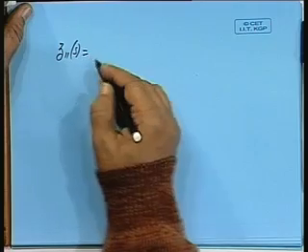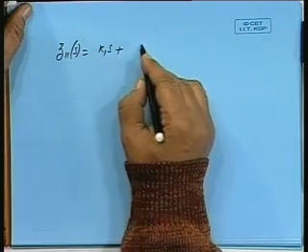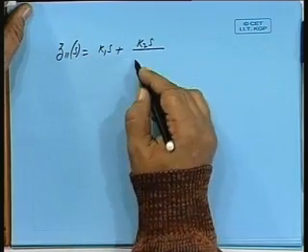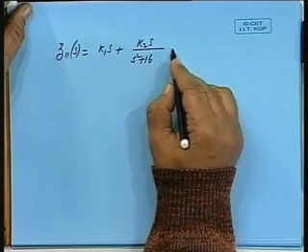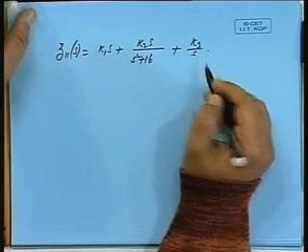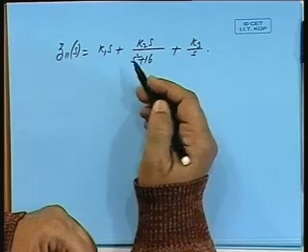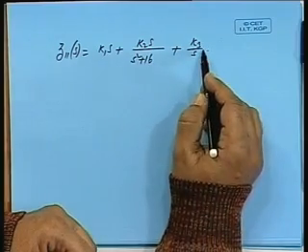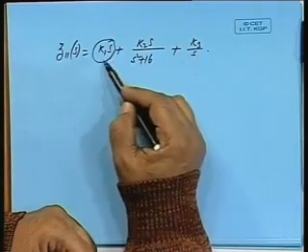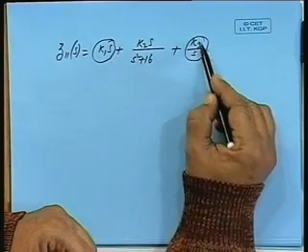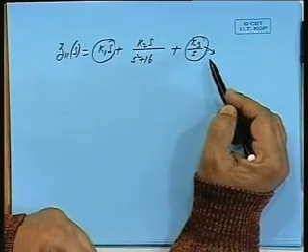Good morning, friends. Last time we were discussing about LC synthesis. We got stuck in a little problem. See, we had Z11S, there was a slip we made. We had something like this, S squared plus 16 plus K3 by S. So, while removing the pole partially, we are concentrating on K1S. Instead of that, it should have been in K3S, okay.